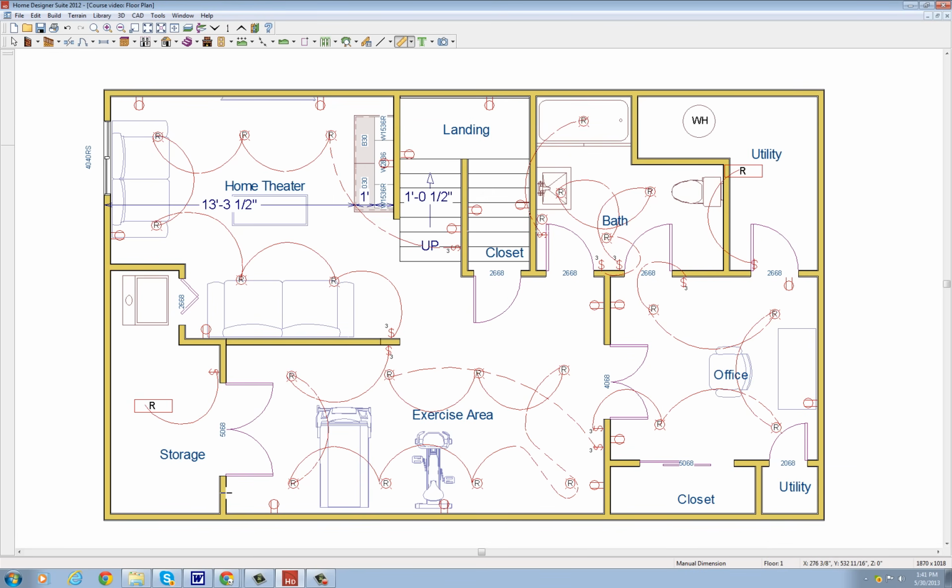Let's go across the exercise area, and there you got 20 foot 4 3/16 inches. And remember that these dimensions on these floor plans will vary depending upon your final resting places where your walls actually have to be, because there's going to be pipes you're working around down there that are against the walls that you're going to have to move your exterior walls in and out from, and other things overhead that may dictate where a wall may be by an inch or two. So you can't be held to these measurements. As long as you're within an inch or two, you're going to be fine.